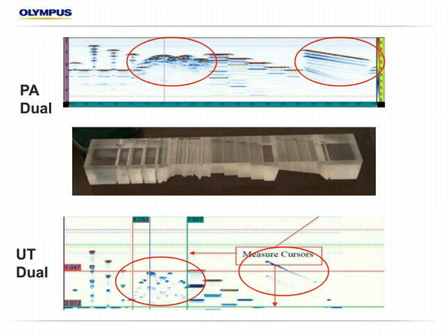But there are 2 areas, really: the simulated corrosion, and definitely the slope. We don't really get a great profile of either one of those areas. And even though we're using a UT dual, by putting it in an encoder buggy and moving very quickly to do a fast scan of a large area, we're probably missing some of the response back from some of these highly oriented areas.